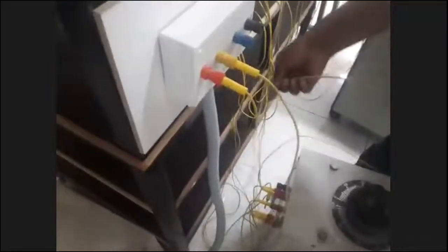See how the connection can be done. Auto transformer. So see the output of the auto transformer. I will do the connection. Here at the input side, we are connecting a supply to the auto transformer. So the R phase is connected to R, the Y phase is connected to Y, and the B phase is connected to the blue terminal. Right. So this is the input.